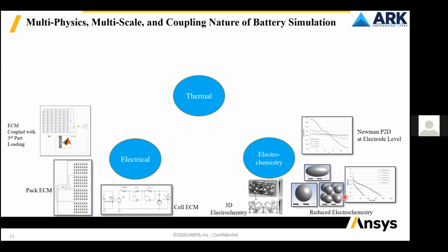So these ECM models are behavior models. They require so-called HPPC data for the model parameter identification. This data can be taken from experiments, or you can get it from ANSYS Twin Builder as well, where you can simulate it for real-time conditions. This is a configuration from the electrochemistry models, and then we can get this HPPC data over here. Then for higher frequency applications, ECM parameters are determined from the electrochemical impedance spectroscopy, that is EIS data.